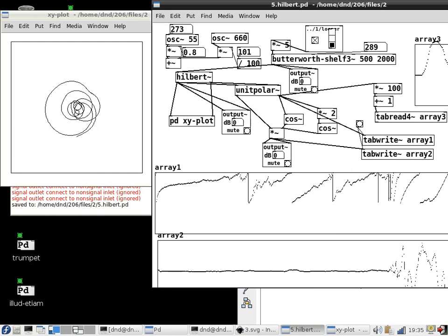Does it matter that they're major chords that preserve the overtones? Yeah, if I put a nice arbitrary chord in there, I don't actually have one handy, but if I did, then it would just be Armageddon. And that's another reason that you would want to pick the channels up separately if you could, because then you wouldn't have intermodulation between the strings and you could play any kind of chord you wanted to.